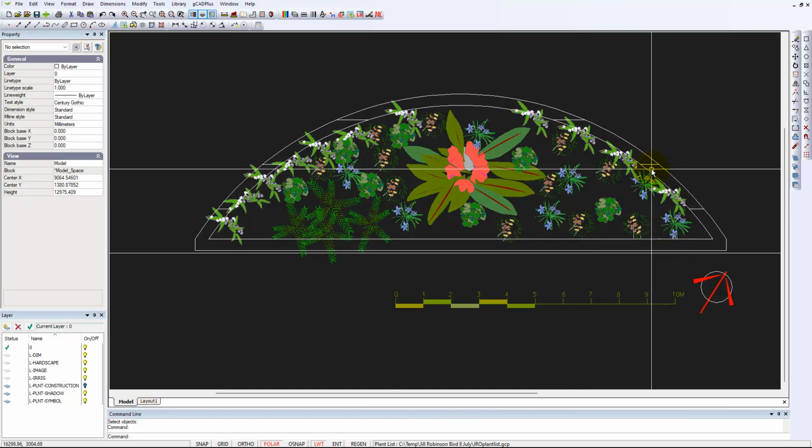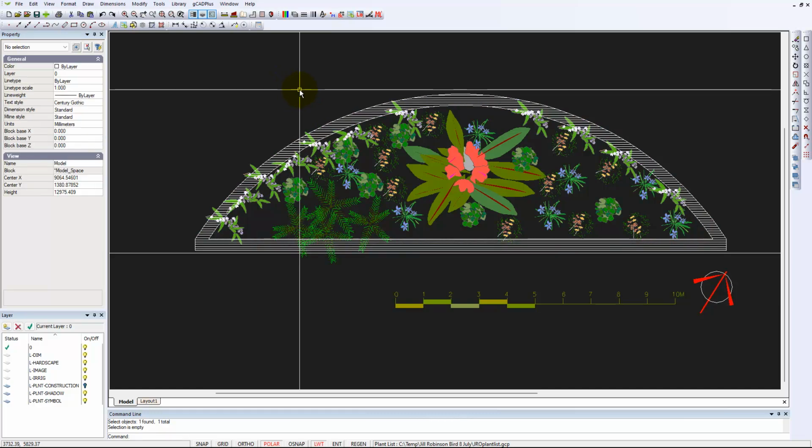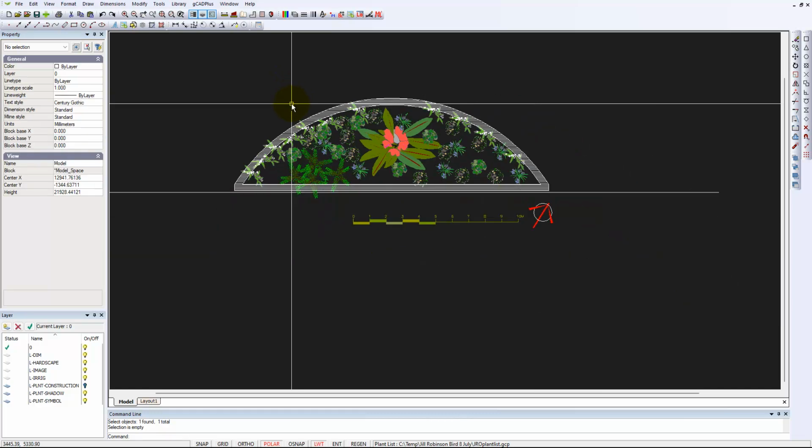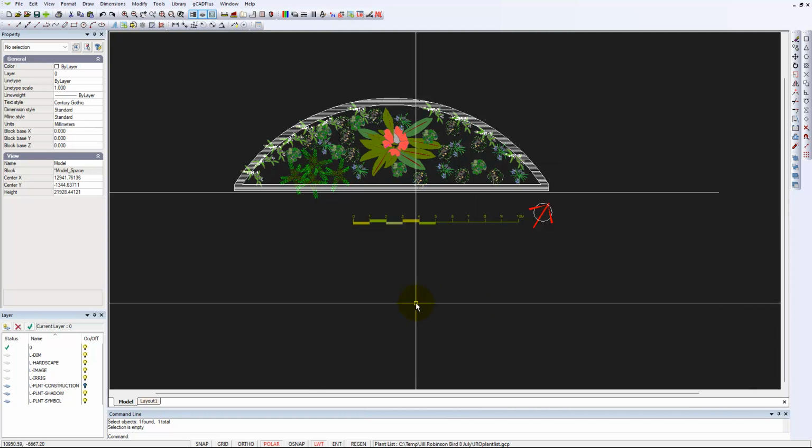Although as I look at it now, if we changed the hatch pattern to say 100, which we were going to do to start with, or even maybe 25, we could probably leave it like that, and that gives us the impression of being a dry stone wall.